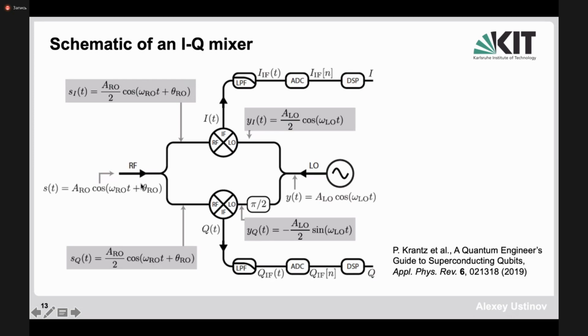So this is the way of using the mixer as a modulator. However, the mixer is a device which actually is designed initially to mix two high-frequency signals. One is the local oscillator. The other one is the signal from your antenna, for example, iPhone antenna, which you have in your pocket. And then, if the local oscillator frequency at the carrier frequency is mixed with the incoming signal, it generates two quadratures of the signal.